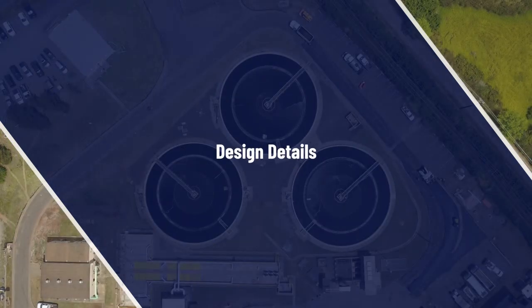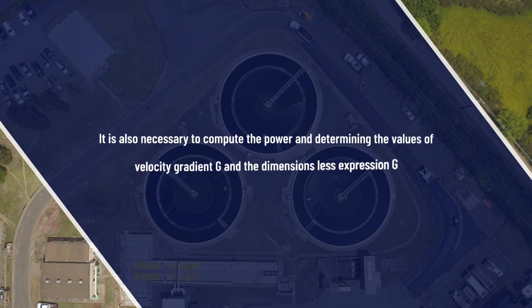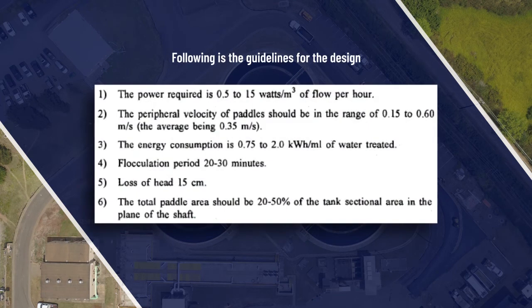Now, design details. For the design of a mechanical type clariflocculator using rotating blades, a knowledge of basin dimension, blade dimension, and speed is necessary. It is also necessary to compute the power and determine the values of velocity gradient G and the dimensionless expression Gt. Following are the guidelines for the design. The power required is 0.5 to 15 watts per meter cube of flow per hour. The peripheral velocity of paddles should be in the range of 0.15 to 0.6 meter per second.